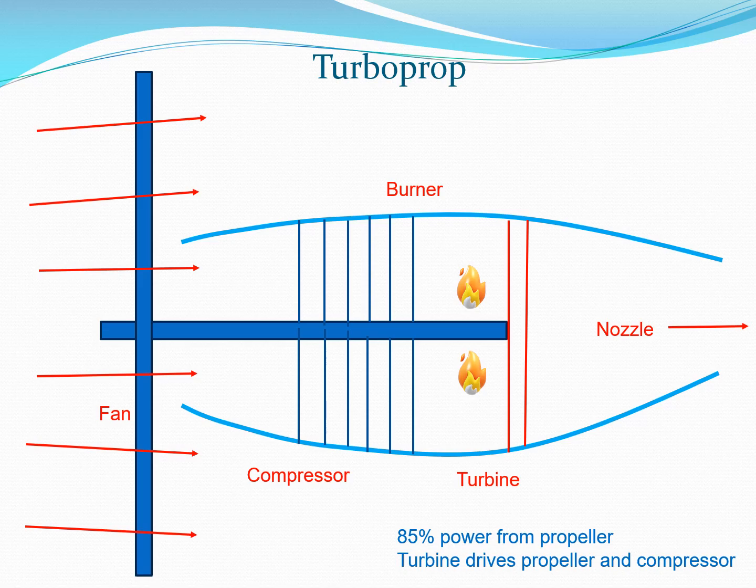So in contrast to the typical piston or reciprocating type of engine which we discussed before, which is used in much of the smaller airplanes that use propellers, turboprops are used in some of the larger aircraft. They have the advantages which accrue to the propeller, such as they can take off and land at runways which are relatively smaller in length. They may be cheaper, and in certain low speed conditions they may be more optimal than jets.